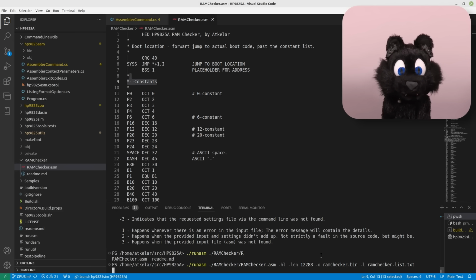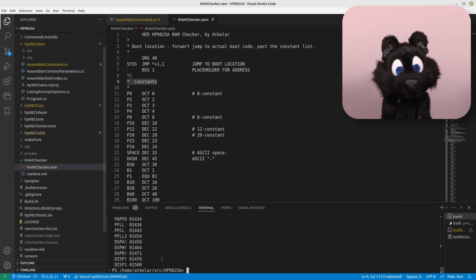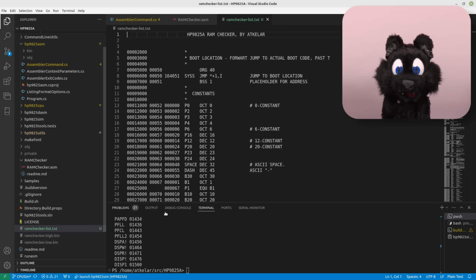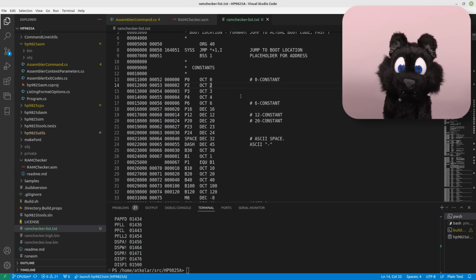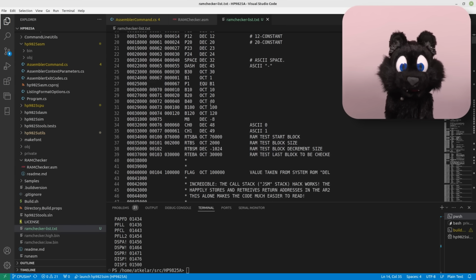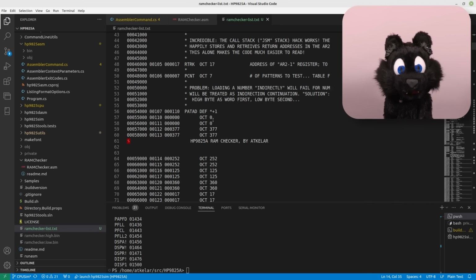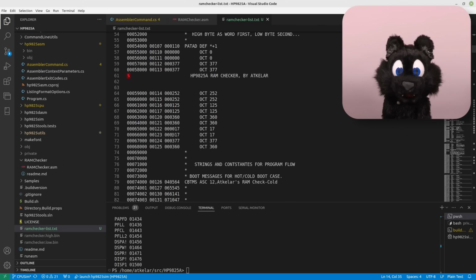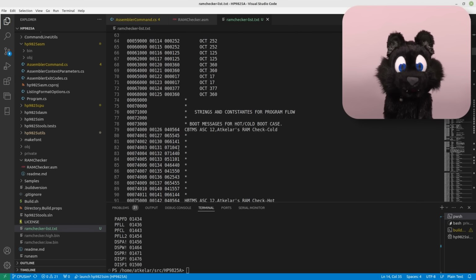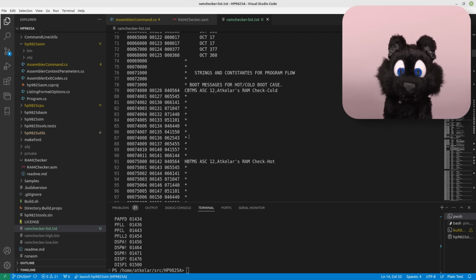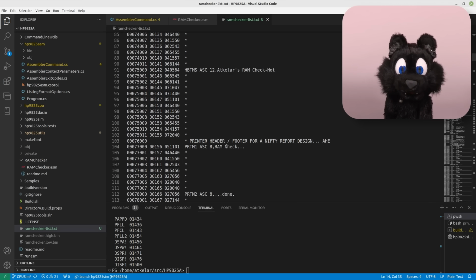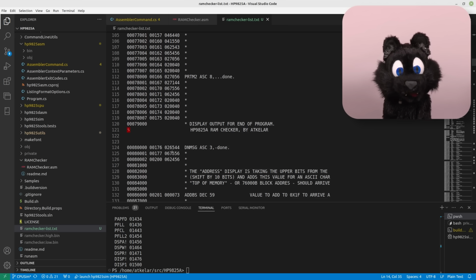To truly and thoroughly test the RAM, one has to do it in situ though. It's not good to test it with an external system or adapter. Those will not stress the RAM chips in exactly the same way. And so, I wrote a bit of assembler code for the CPU that could be put into the system ROM as a drop-in replacement. It should exercise the RAM by writing and reading back different patterns and also somehow report back the results.